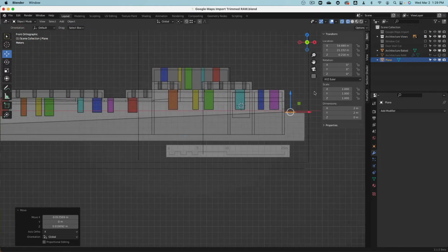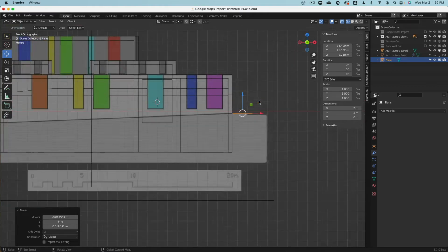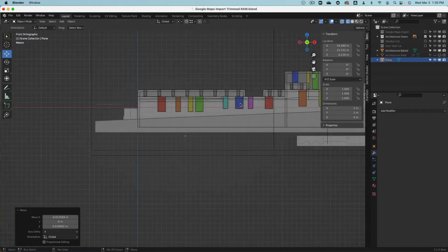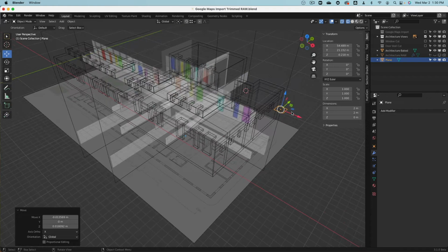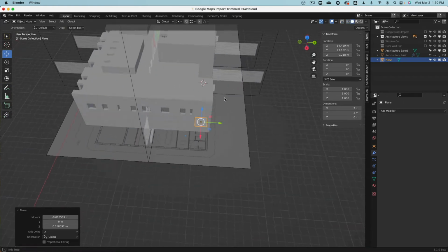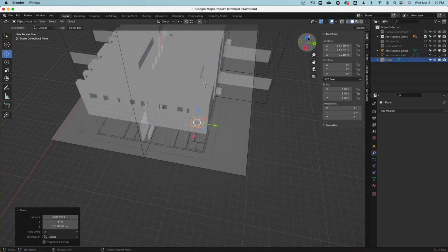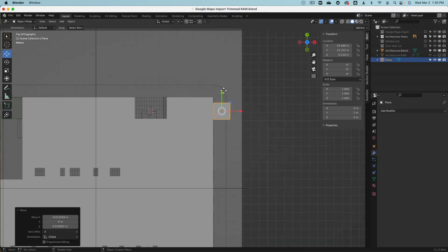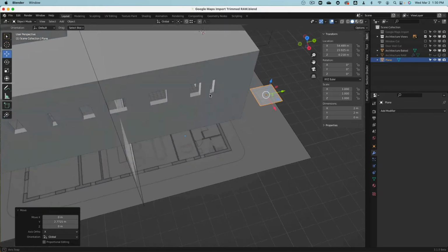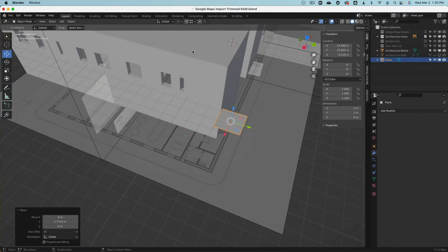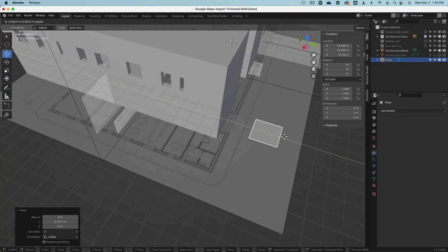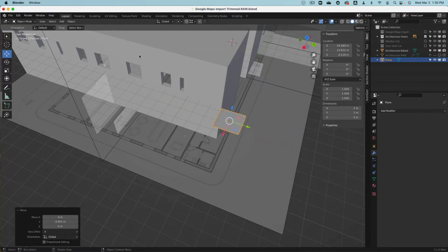There. Good, that's kind of like the street, and then there it goes down. So how do we continue? I will go maybe to this top view, bring this to there. Point select, move this to here, hold control, snap it to there.